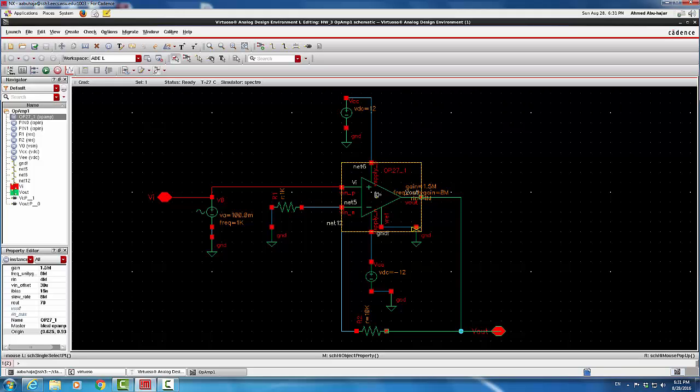So sometimes we put capacitors in the op-amp to make sure that the op-amp will be stable in a feedback system. So we add those capacitors. We call them frequency compensators or frequency compensation circuits, as we add those capacitors inside the op-amp to make the op-amp stable. All what we learned in this computer simulation is basically how to add a path for our library, and we were able to port in an op-amp.